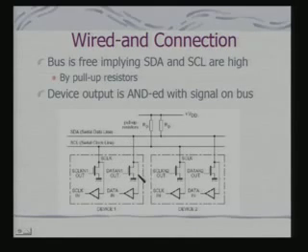These are all open collector interfaces or open drain interfaces. You have the resistors connecting these lines to VDD, the drain voltage, so that the normal condition for all of them is high, and effectively this connection is nothing but wired-AND. So, a device can pull the line low. This is the basic structure and interface of the devices for connecting onto the I2C bus.